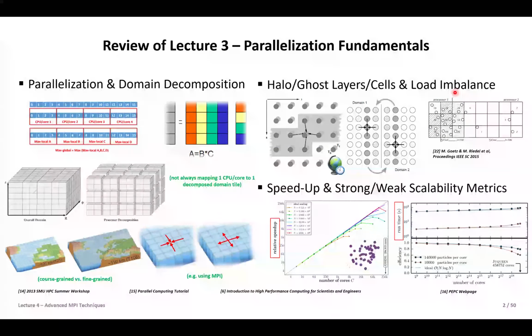Then two words which were also incredibly important are speedup and strong and weak scaling. They are related and also limiting us, right? So speaking first of the relative speedup, this is important to have strong scaling. You basically always have the same amount of domain that you want to simulate, and you keep that constant, right? The work per processor and per core constant. So here, different examples. Don't get carried away by the different colors. Per color, it's still constant.